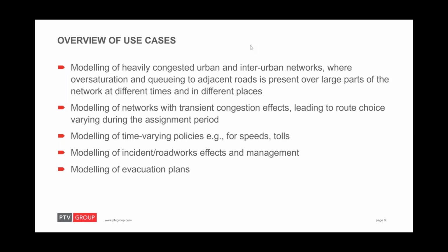Then modeling of networks with transient congestion effects. Let's say you have work zones and so forth where certain times of day might present different congestion than typical. You can model that using time varying attributes with the dynamic assignment. Then if you have, again, speeds or tolls that vary by time of day, you can also model that with dynamic assignment or simulation-based dynamic assignment.